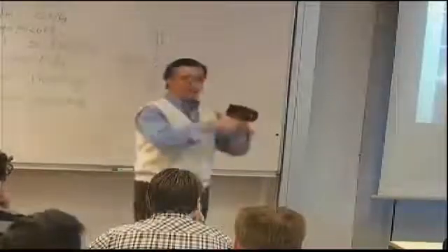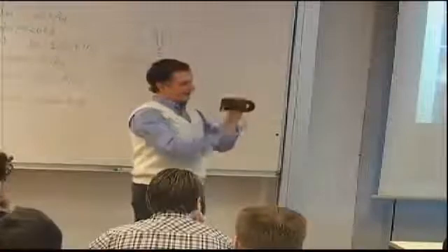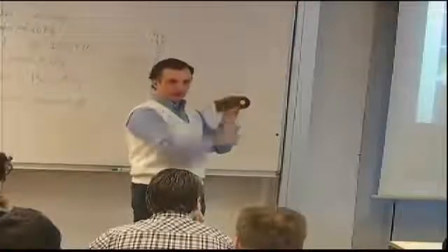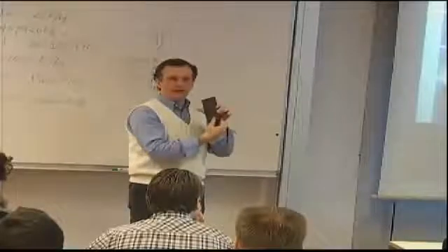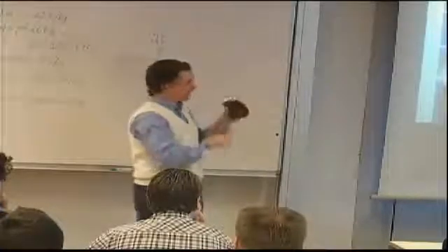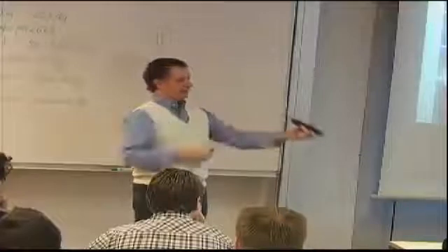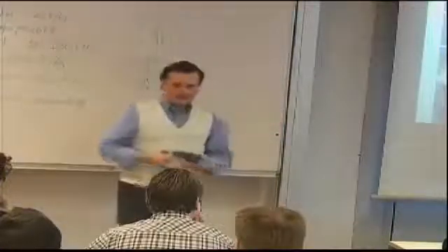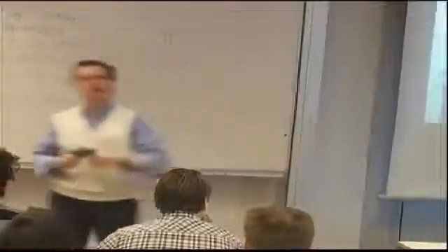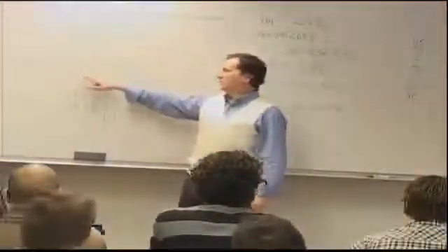You will see that the hole has elongated in one of the two directions, which means there's a bearing failure in that direction. You'll see that the material has moved out of the way, you have local compression failure. And you will see, if you look at it on the edge, basically a huge delamination where the layers have separated. And by the time it goes all the way around, we will have a vote on what is the load to failure of this. And the units we will use will be fully grown female elephants.